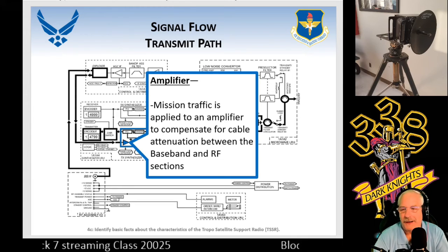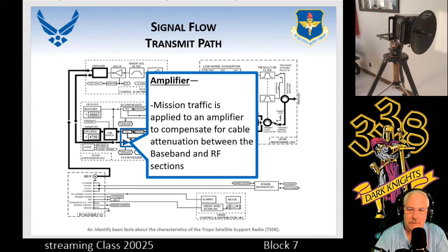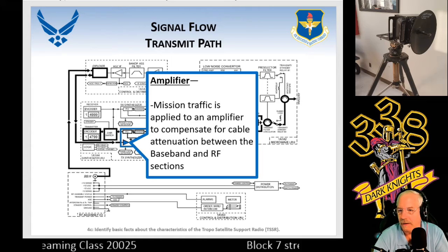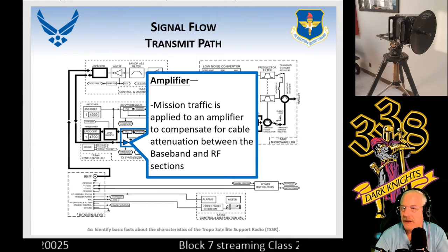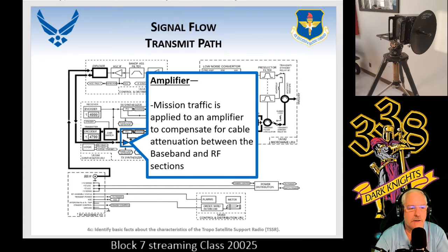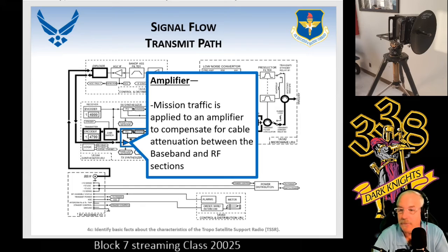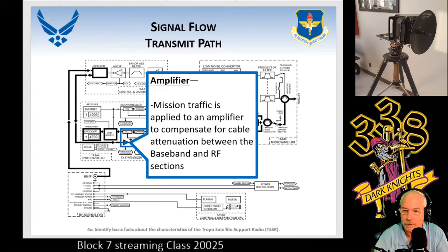The best way with that is something called a compression amplifier, and I'm not sure if they taught you that in Dolan Hall. The idea behind what's called a compression amplifier is it will always amplify, but if it reaches a certain level, it will compress the signal to make, oh gee, sounds like AGC, doesn't it? Make that output a constant level. So whatever the varying input is, depending on the cable, whether it's a 2-foot or a 150-foot, it's going to compensate for that.